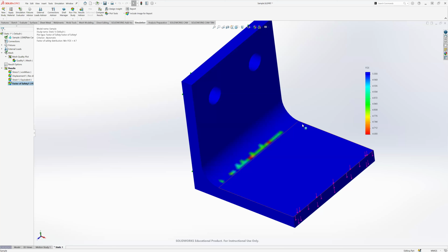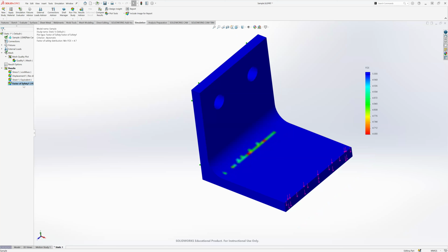Typically for most applications, you're probably looking at a factor of safety between 2 and 3 somewhere. Again, aerospace, I believe, is in the 1.6 range. You can look all of this up, and it probably depends on the specific application as well. So that's a good factor of safety plot. Any questions about factor of safety plots?